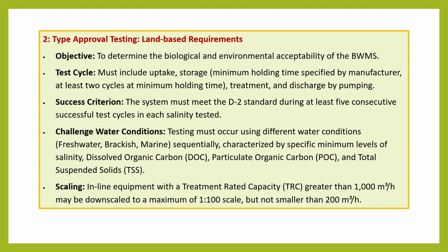tested. Challenge water conditions. Testing must occur using different water conditions: freshwater, brackish, marine, sequentially, characterized by specific minimum levels of salinity, dissolved organic carbon, DOC, particulate organic carbon, POC, and total suspended solids, TSS. Scaling. Inline equipment with a treatment rated capacity, TRC, greater than 1,000 cubic meters per hour may be downscaled to a maximum of 1:100 scale, but not smaller than 200 cubic meters per hour.